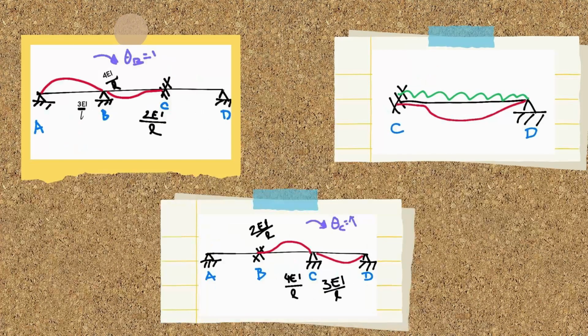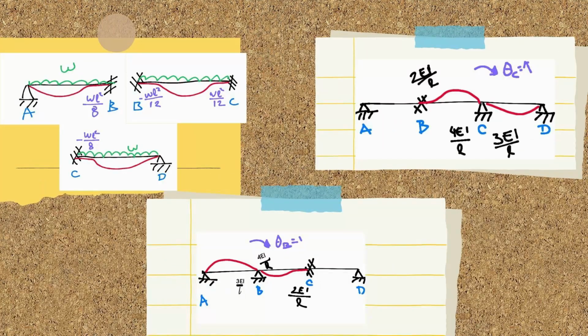Now we put into practice the angular stiffness coefficients, returning to the example of the beam with 3 simple supports. I have to release the degree of freedom, just as I restricted or embedded them. In that case, we embed the node or support in the middle, so that is where the moments we are looking for are generated. Having all these moments or unbalanced forces previously calculated, the linear and angular ones.